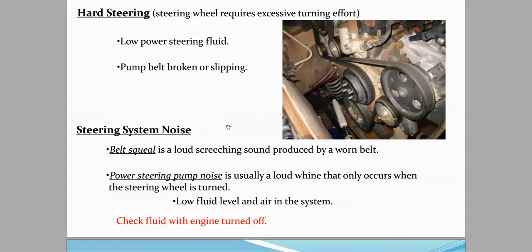If you hear a screaming and screeching sound from the engine side, it means your belt is squealing, and it makes a pinging sound that identifies that your belt is not well, and you have to lubricate it or completely replace the belt.